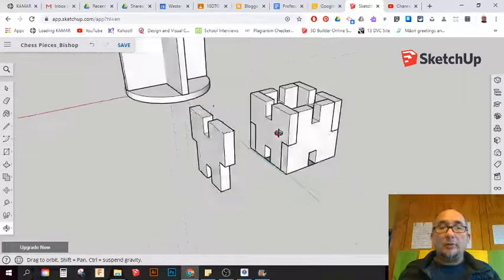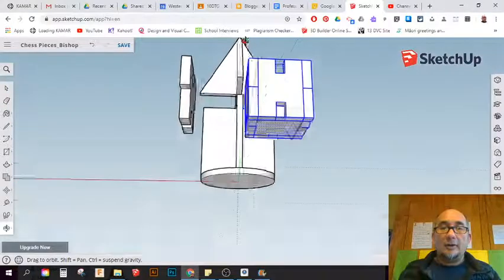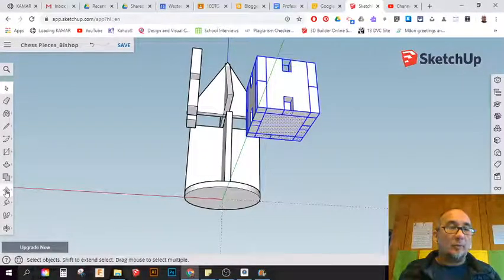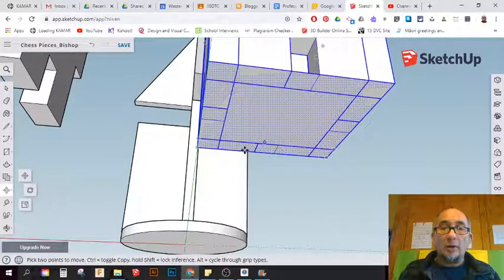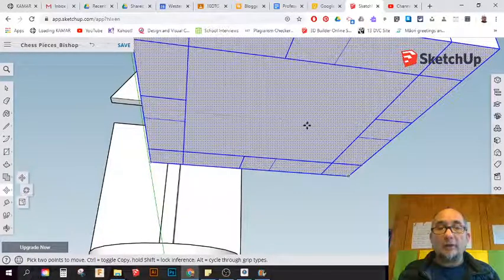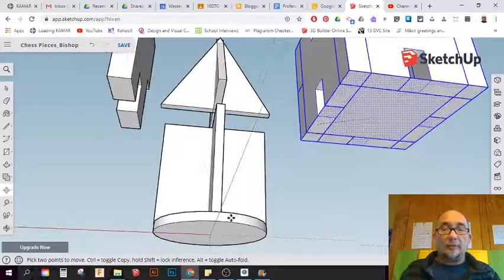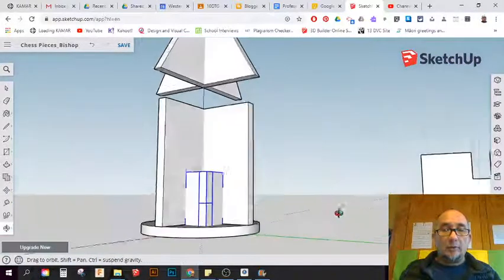And now we're going to move this whole assembly. So selected all this. Look at the bottom of it. Choose our move tool. I'm going to move it from this midpoint and that midpoint where those two intersect. Let's see, is this right? Let's say that that's right. We're going to move that to the origin first, and then we're going to move it up.